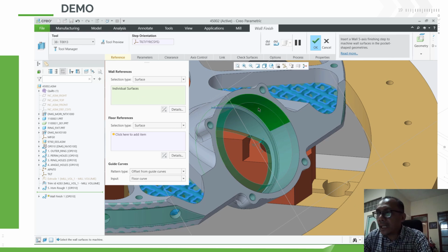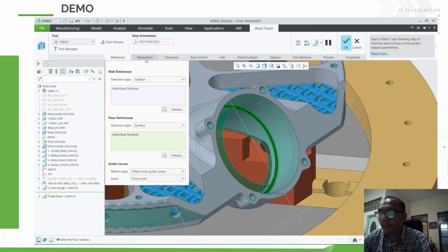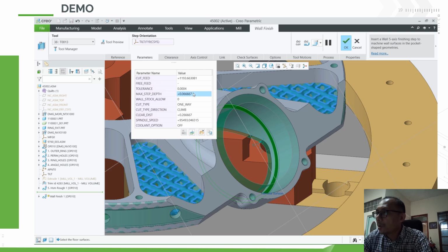Okay, clearance is normal there. Then you have control of contact point and lead angle. So there are good defaults here, but it allows you to have a lot of control because the tool is going to be tilted away from the walls. Then how are we going to link them together? Lots of different options here. Now let's review this barrel cutting the walls of the part.